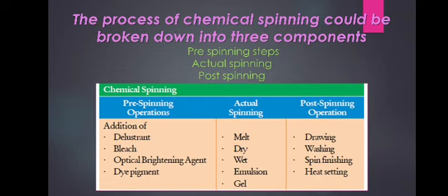It is the wet spinning method because it is passing through an acid bath. It is a liquid solution, and directly this solution in the spinneret passes through the bath or a liquid substance, maybe acid or any substance that solidifies the yarns. So it is passing through a liquid substance, so it is known as the wet spinning process.